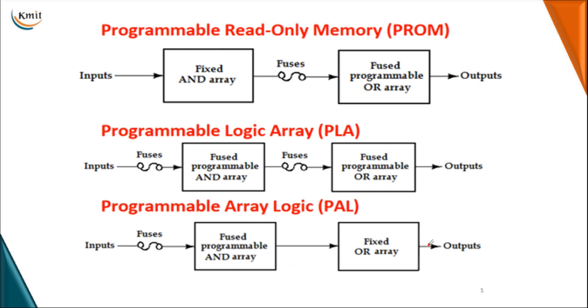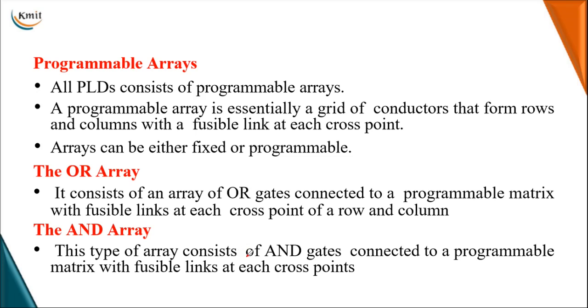Whereas in programmable array logic, you transmit the inputs through the programmable connections to the array of AND gates, and outputs of AND gates are connected to the fixed OR arrays. So here the inputs are not programmable, only the outputs are obtained from the fixed OR array in your PAL. Now, let me move to your PLA.